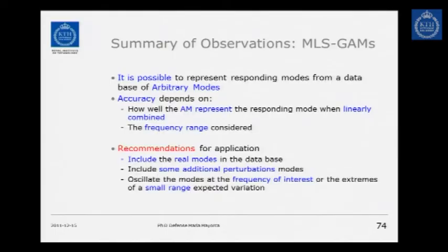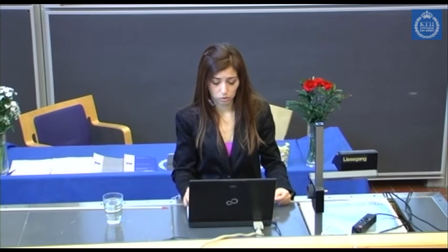It is possible to represent the responding modes from a database of arbitrary modes, but it depends on how well your database of modes represents the mode that you want to predict, and also how wide your frequency range is. The recommendation is to include a real mode, and then some basis of perturbation of that mode. So you don't have to model 128, but some basis of perturbation that allows you to fit to the expected perturbations that you have.